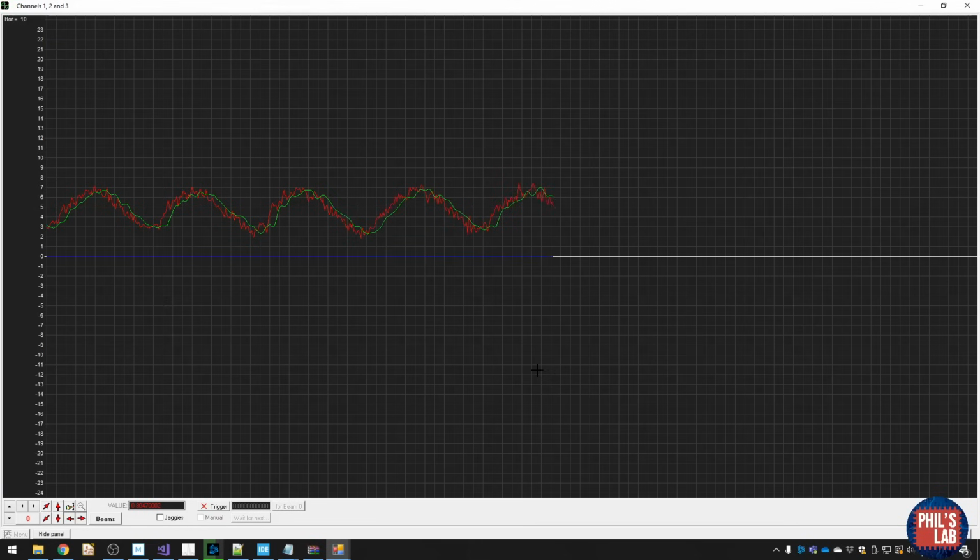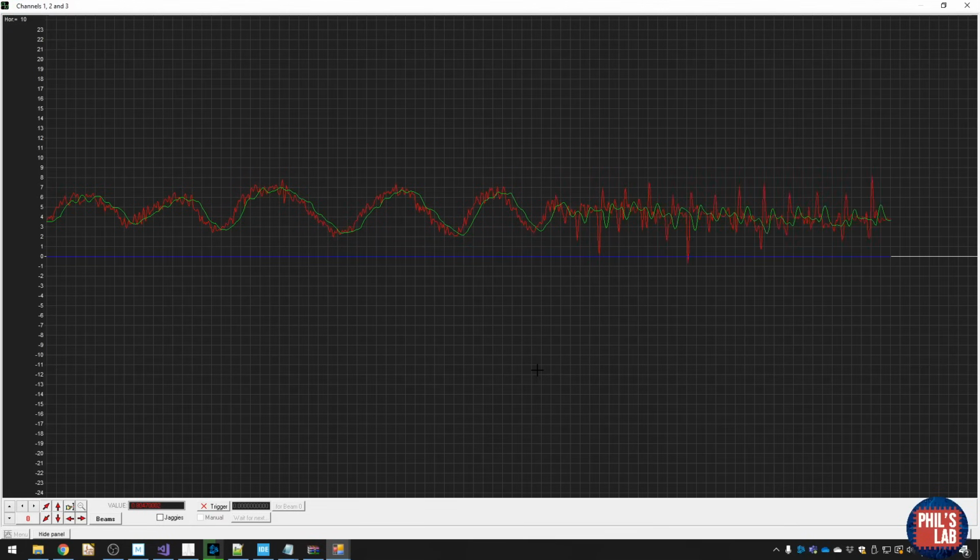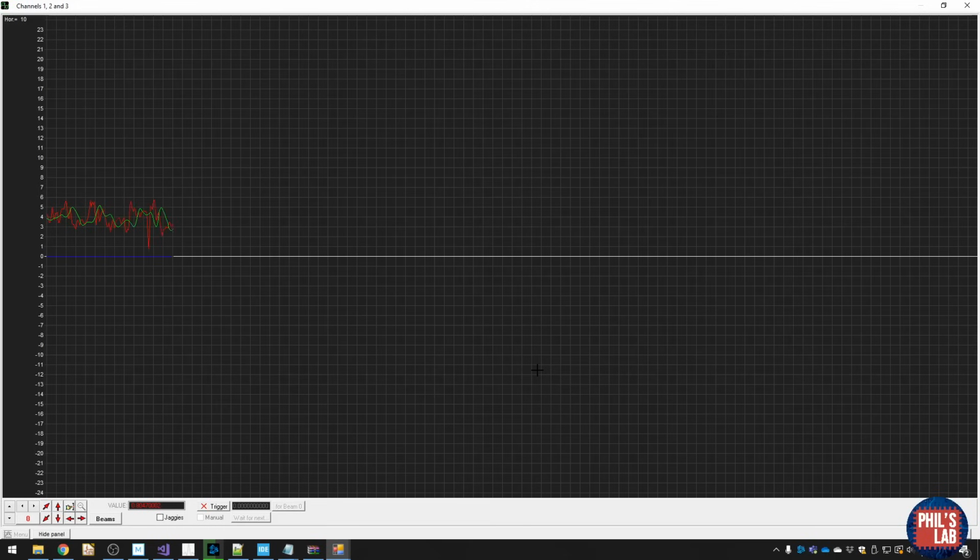This depends on your cutoff frequency and how much filtering you're applying, because the more you filter the signal, the more delay you're going to introduce into the signal. And this is exactly what we're seeing here. If I speed it up even more, you can see the high frequency information is really filtered out, which is what we set our filter to do. So it works really well up to the cutoff frequency, and as soon as we increase the frequency of the data, then of course we will lag and reduce the amplitude. But yeah, this is a really nice visualization of our FIR filter actually working.